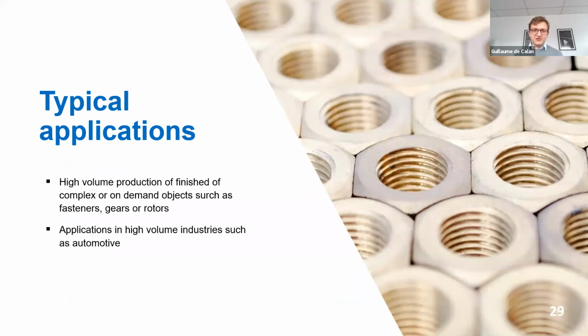It's a technology for production of finished, quite complex parts or on-demand parts, but still, this is a technology which is used by people looking for volumes. Of course, we're very far away from what MIM, the real MIM technology, will do, but you can print more complex parts, you can print smaller series. So it has really that range where it's made for production, but production of complex parts or production of medium-sized batch.